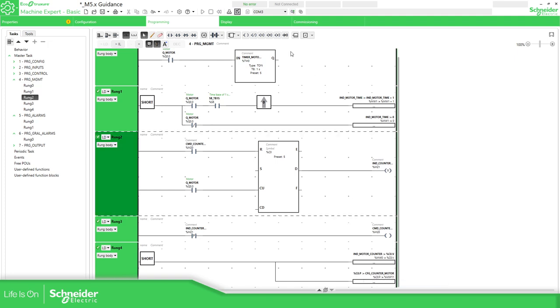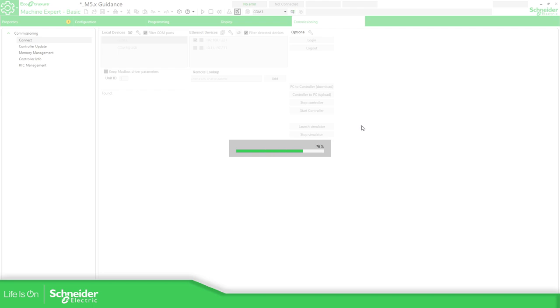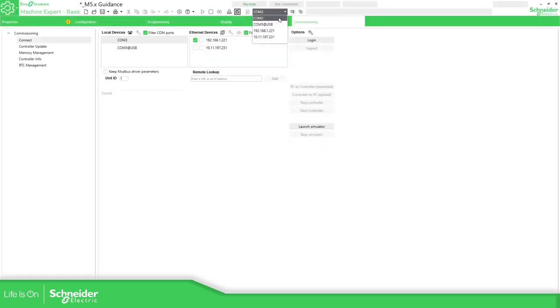If we go to management, again, see, yes, MW0 is the actual value, and this one is the configuration of the counter. So what I'm going to do is to connect to the PLC, download this example that we have done, and see if it's working or not, just to show you about the configuration and communication to an HMI. I haven't changed the port, my bad on there. Okay, now it's going to communicate with the PLC.